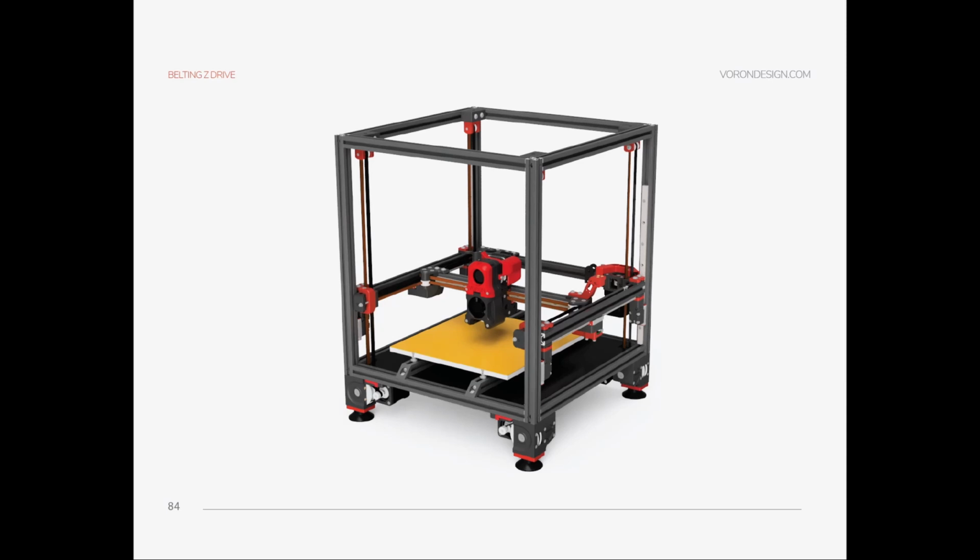Again, since it is flush in here, just run one of them, and while you are putting this screw, by the way, you can use a zip tie or a rope to hold your gantry. Just zip tie from here, for example, or rope from here and somewhere in here, and slide your carriage and screw them. And after that, run one of your Z belts.